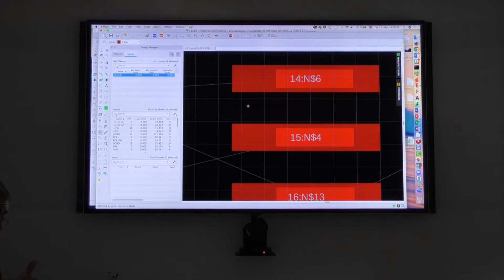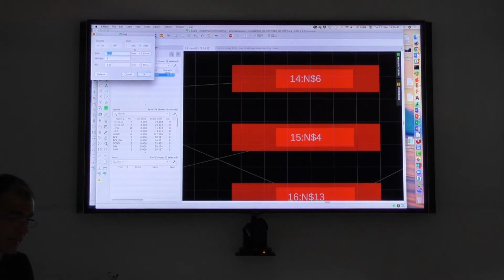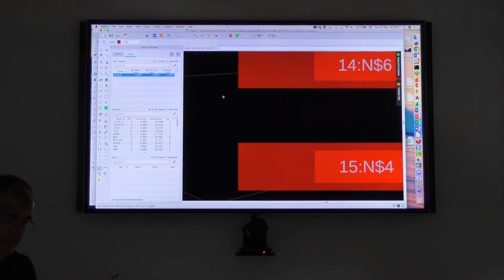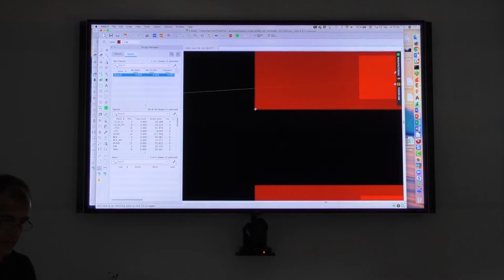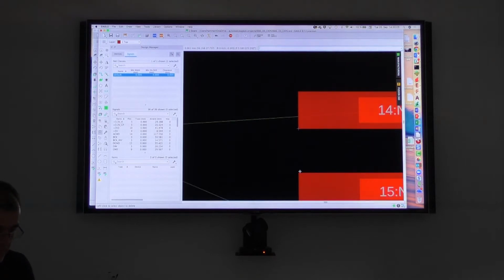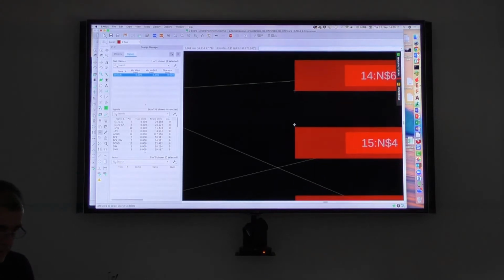I don't have a real simple way to do it, but what I do is I switch to a finer grid. I simply say 0.001, that's fine enough. Then I use the mark command. That's something to set a relative origin. I go there, zoom in. Okay, I have the notation switched on, doesn't matter. I click here, then I go down there, and you see the coordinates. No, it's the wrong place, I have to go there.